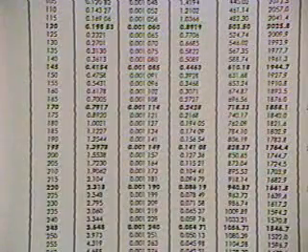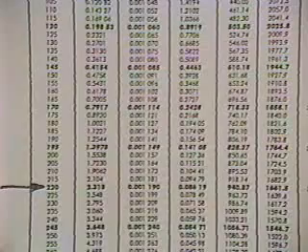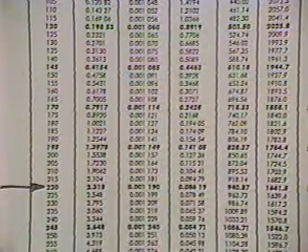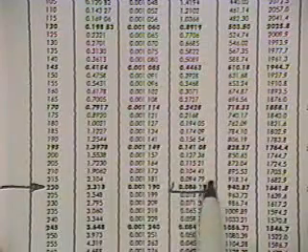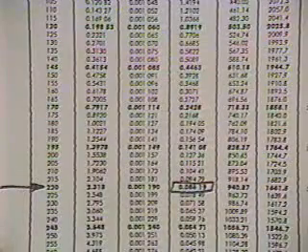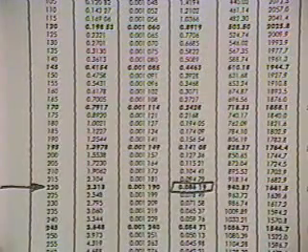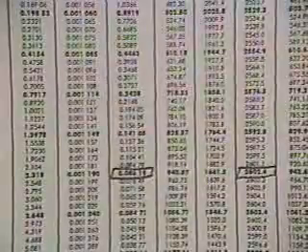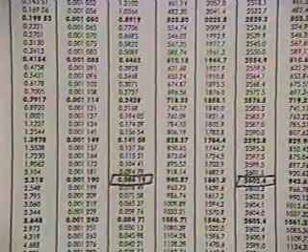We're starting out at a condition of 220 degrees C, saturated vapor. From the tables on page 48 at 220 degrees C, you come over and read a value of 0.08619 for the specific volume at saturated vapor conditions, and you can come over at UG and read a value of 2602.4 for the saturated vapor condition.